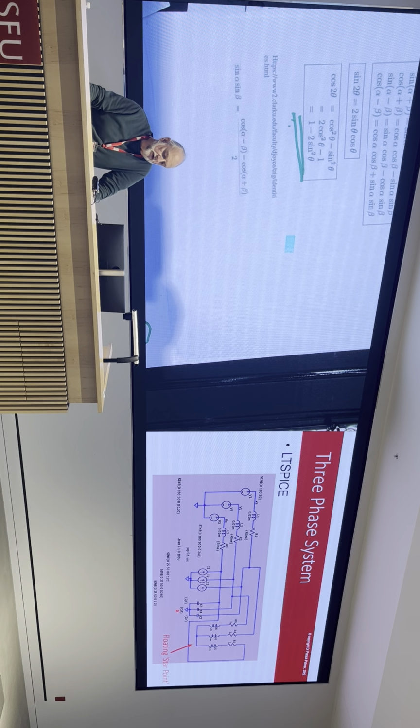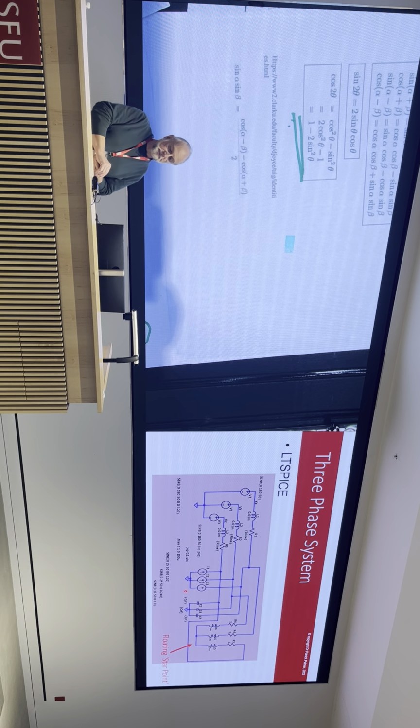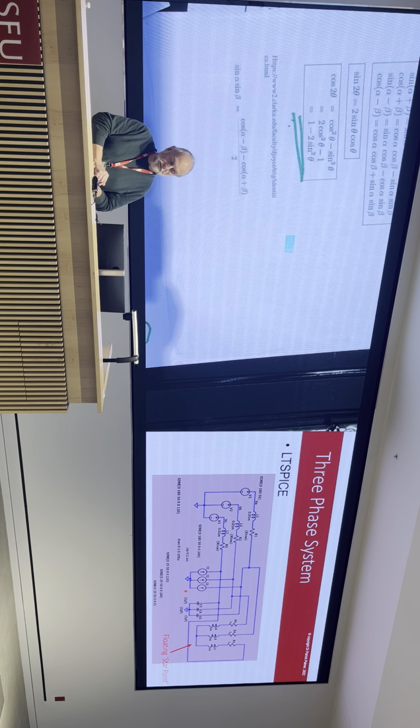So what we would often do is put in capacitors across the supply to provide some reactive power to compensate for inductive type reactive power over here. We've also got inductive reactive power here as well, typically. Can't remember what I was doing with these particular currents, but the idea is that everything is balanced, all perfectly balanced. And then we end up with a very nice system with absolutely dead flat power. Now I'm going to show that next time.